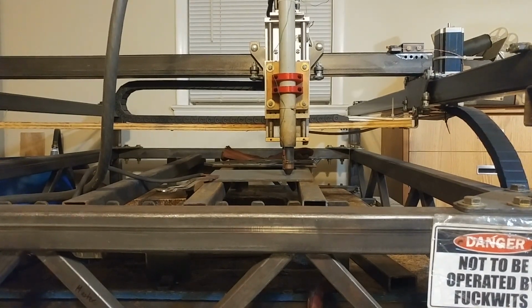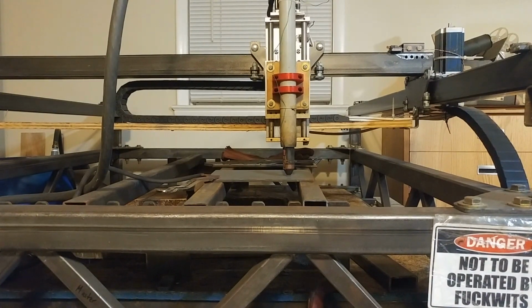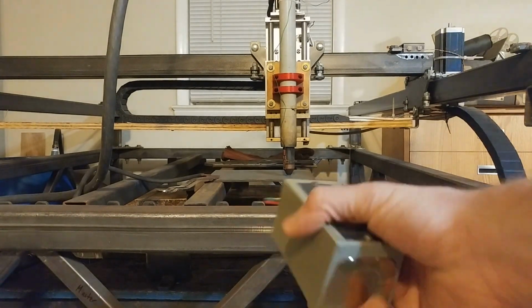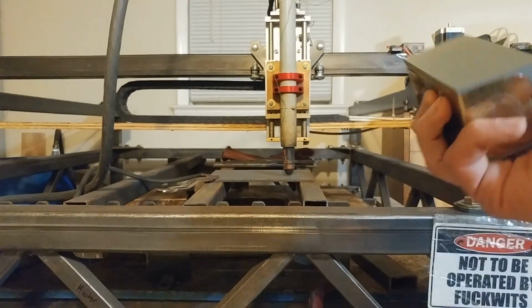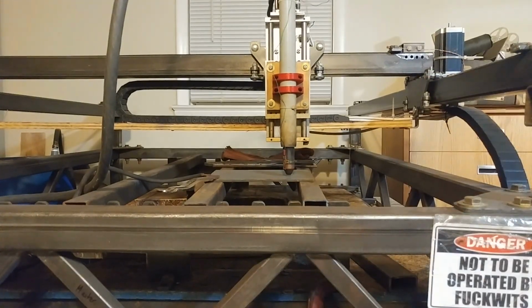Firstly, it's a good example of how flexible you can be when working with LinuxCNC and HAL, right? Normally the THC puts up and down signals to the parallel port breakout board, and then LinuxCNC reads that, forwards it over to the THCud component, and that controls the Z height accordingly. But those signals don't need to come from a THC, right? They can come, for example, just from big old mechanical buttons, and you hook those up to your parallel port breakout board, and that also works.